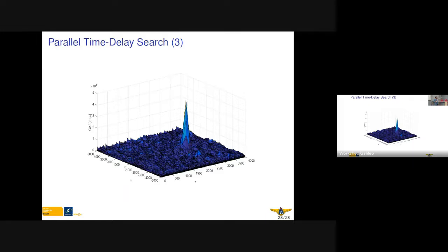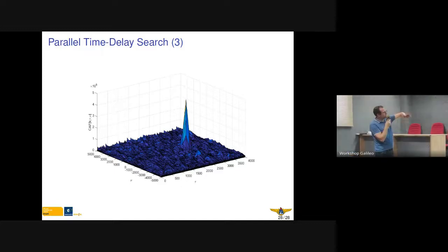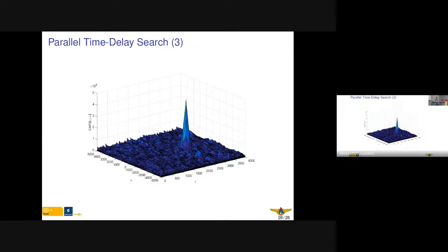But the resolution in the time domain is a resolution of samples, and the Doppler resolution can usually be chosen manually or adequately. We can evaluate this cost function really nicely. We just need to end up in this concave region, and then we can hand over to the delay lock loop, phase lock loop and frequency lock loop, and we will talk about this tomorrow afternoon. So thank you very much for your attention.